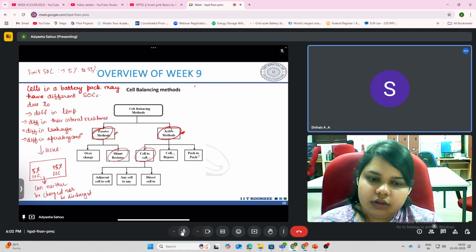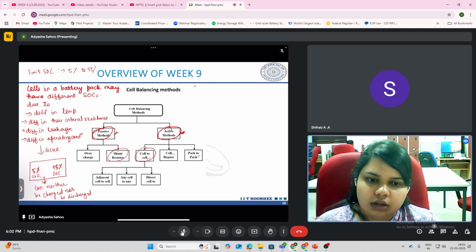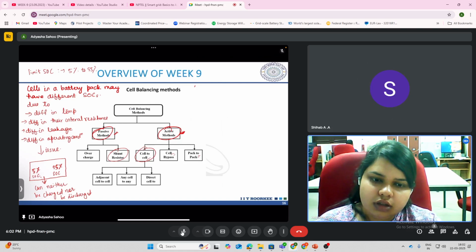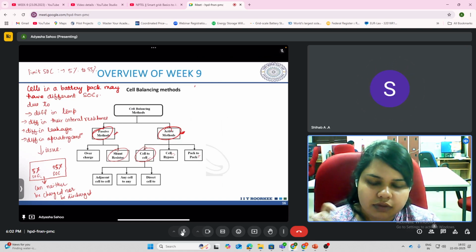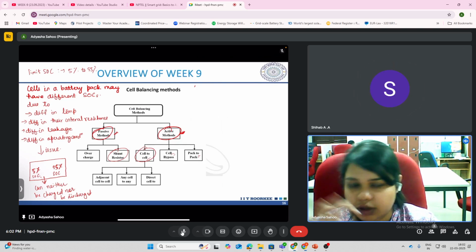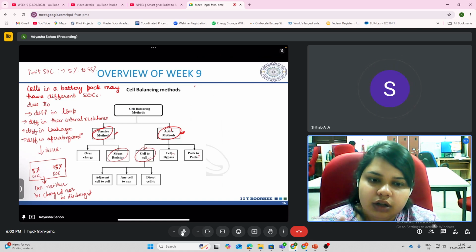If it wants to operate always in grid connected mode, the grid will always be in AC. So for that, it will be simpler if it is only an AC coupled microgrid. Once you are in synchronism, if you have a DC coupled microgrid with the grid, then you need sophisticated converters to match for synchronism and also for power conversion. But if you have an AC coupled microgrid, you can directly add the AC bus to the grid.